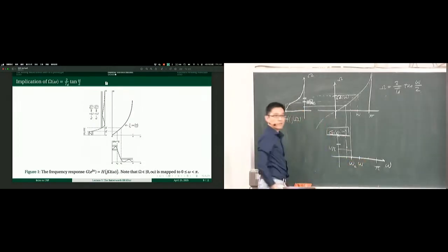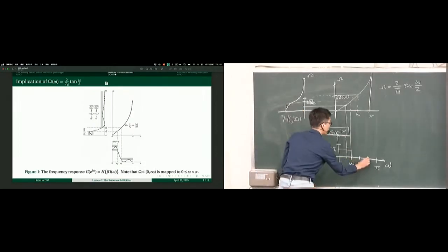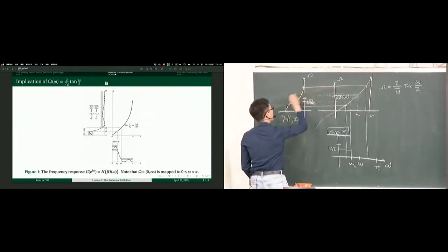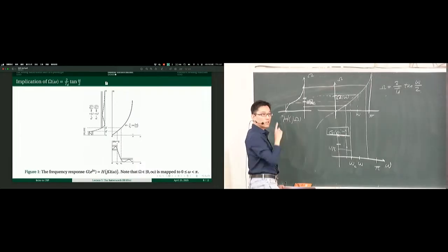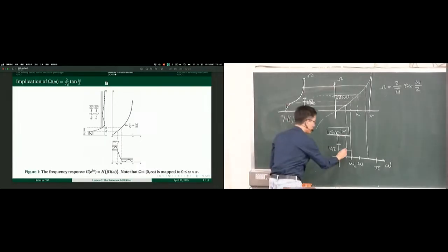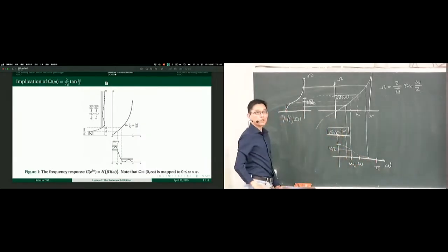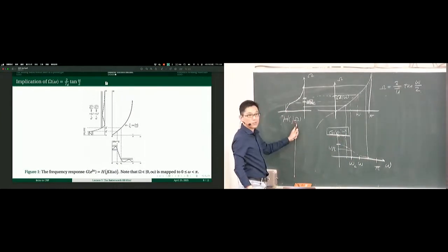How about this frequency? This frequency goes here to top. That frequency goes here. Oh, the gain is very small. So you can just keep adding more and more points, and you get this frequency response, which will also be monotonically decreasing if your prototype is Butterworth.